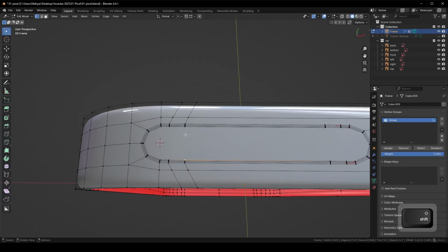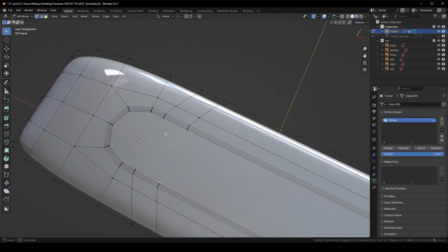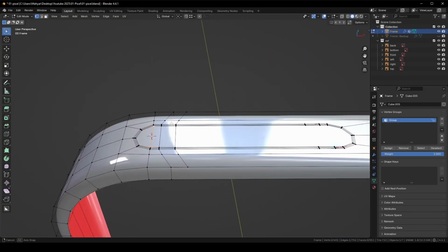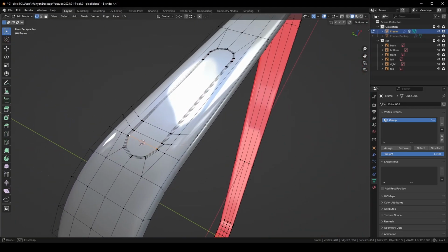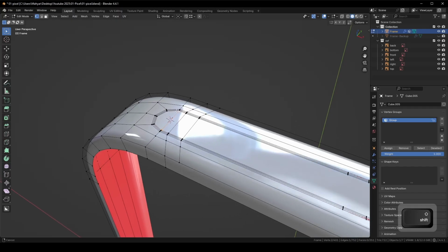To dictate how triangulation should work, I will connect these ones, J, so that we don't have stretched surfaces. Blender itself in the background creates surfaces by connecting the vertices together, and by cutting these ourselves we are dictating to Blender how it should cut the surfaces.